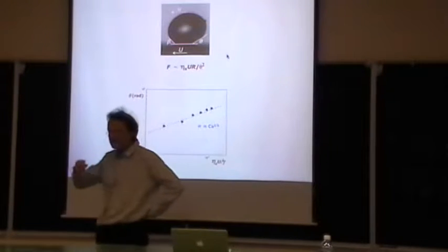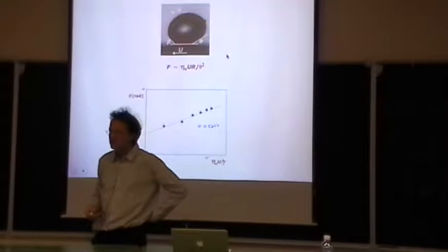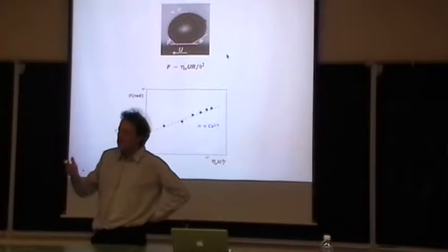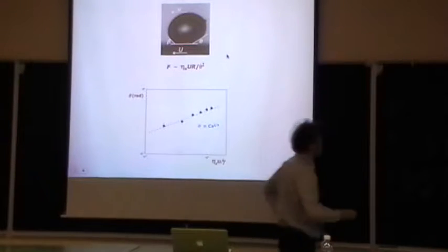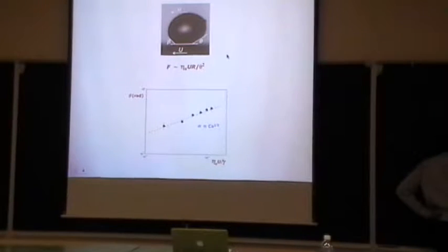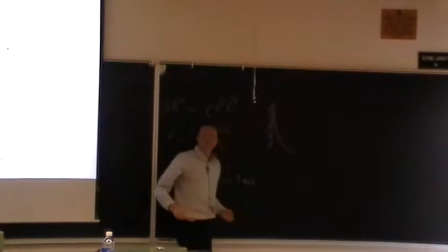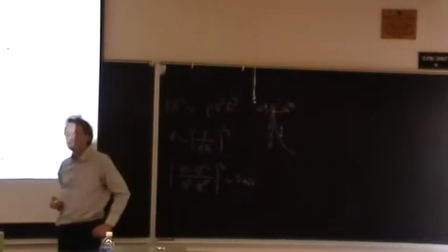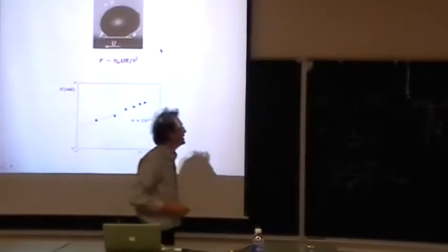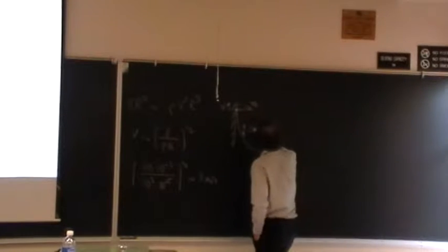And if you want to understand where it comes from, this is very close to a problem that I cannot not evoke in a course devoted to wetting and capillarity, which is the Landau-Levich problem. When you draw a solid out of a bath of liquid, you entrain a thin film, and the scaling for the thickness of this film is capillary number to the 2/3, and the scaling for the transition region where you form this film is capillary number to the 1/3.